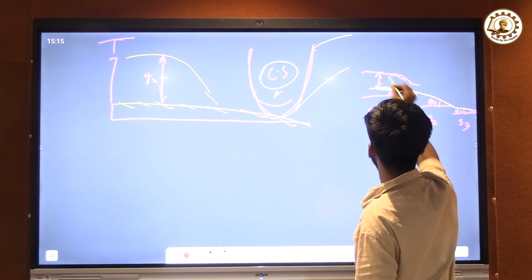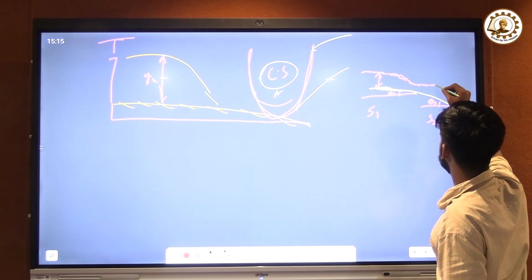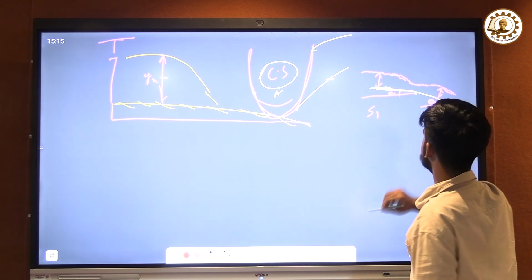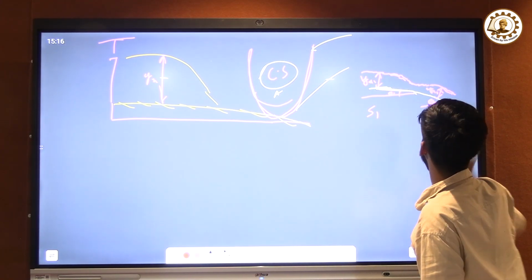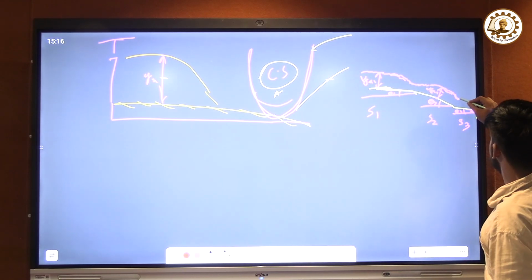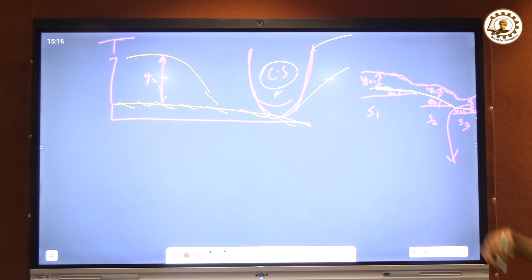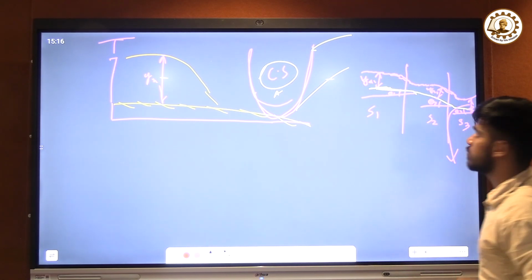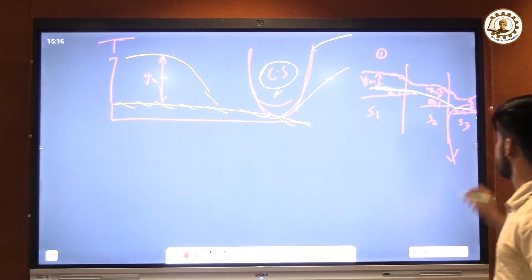Then here it is uniform. Now here what happens? It will have a lower depth. Now after certain time it will gradually increase like this. Then we can have another normal depth, yn1, yn2 we can write. And for this channel, the depth will automatically vary with slope in uniform flow, and the uniformity of the flow remains throughout a single section of slope. And then we can write this yn3.